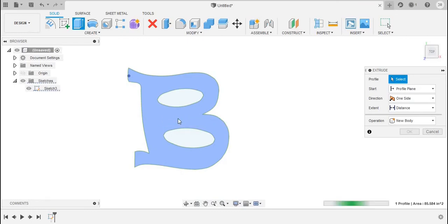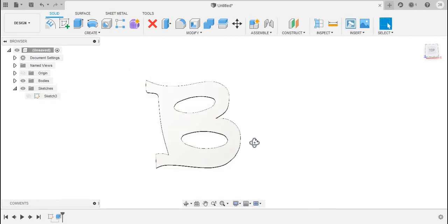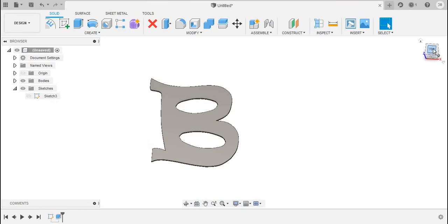So I selected that object. I selected Extrude. I came down here. I selected the B shape, and it's processing. There we go. Say I was going to do that out of 1/4 inch material. I do it that way. I type in 0.25, and as it's processing, I'll show you it turning, so you can see that three-dimensional effect. There we go. Now I'm going to tilt it up, and you can see how that has thickness. But in this case, I just want to see the top.